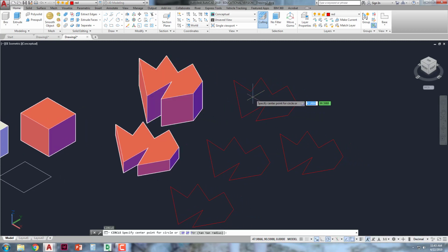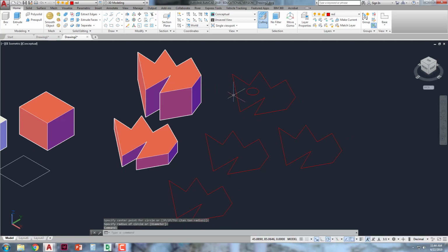Here's a problem. What happens if I have a circle here? Oh, he looks like a little chameleon or lizard or something, doesn't he? Like that's his mouth and his eye. All right, so I want to extrude, but I need that to have a hole in it right there. So I'm going to select, oops, can't do it. I'm going to region or join. Let's just join.